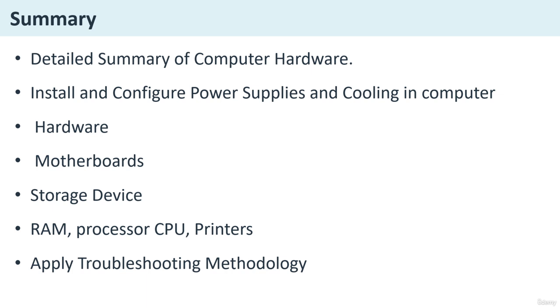Now, calculating the power requirements. To choose the right PSU wattage, check CPU and GPU power consumption, that is the TDP readings. Then add power for RAM, drives, and fans, that is from 50 to 100 watts. Now, fully modular PSU lets you remove all cables for better airflow and aesthetics.